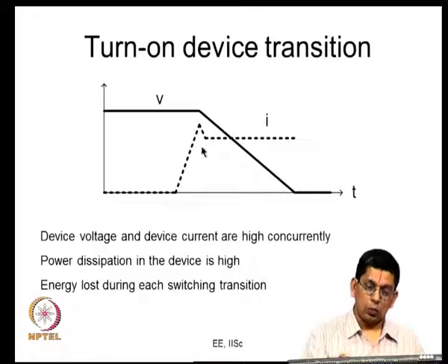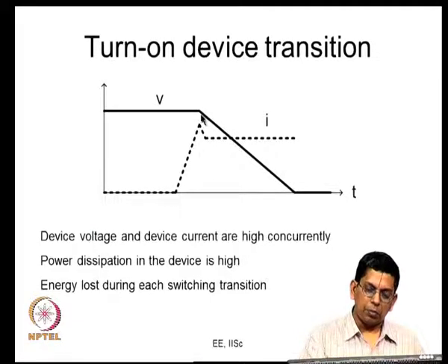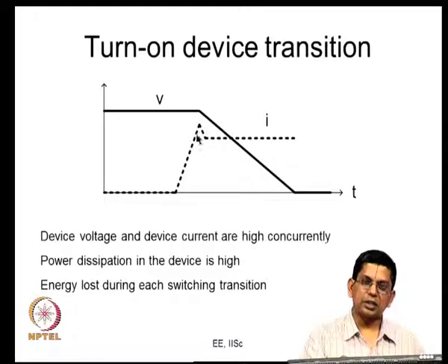Now on top of it, what you really have is a little on the higher side. This is basically the reverse recovery current. It is just the load current plus the reverse recovery current of the diode that flows through, and after that it is a steady current here. So well before the voltage starts falling, the current has reached its peak value.